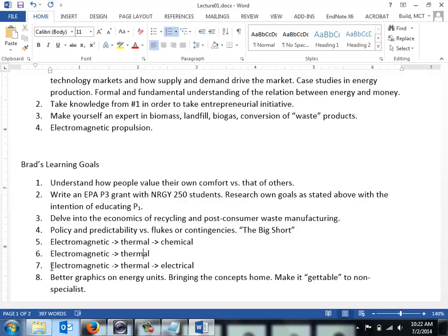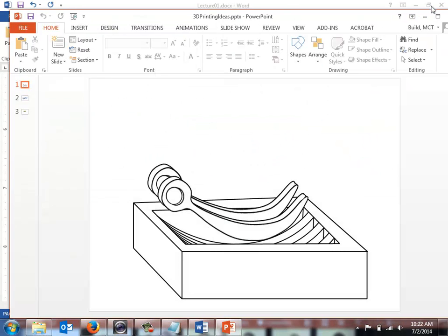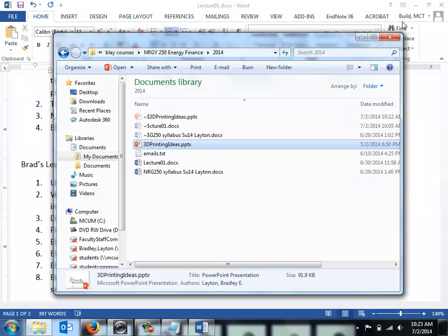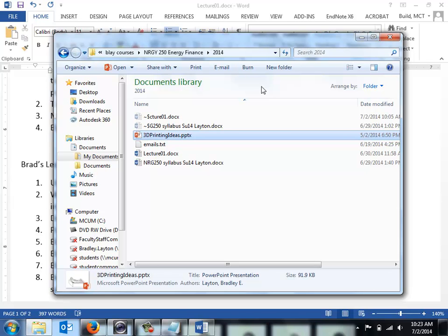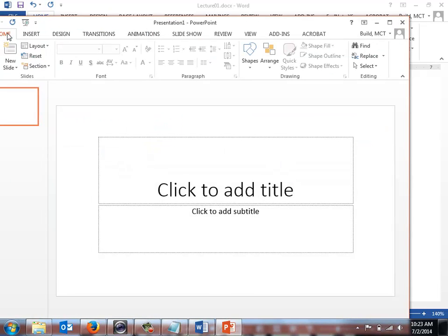Well, it'd be underneath, so you'd have your solar thermal over the top of your PV, and then there'd be your airspace, and the photon would come all the way down in, and capture the heat before it went in, so you get photons. Oh, well, maybe, I think if you did that, you're going to reduce the efficiency. It just depends on how much efficiency you would reduce on the photons going in, because that's what you're looking for, the electrical conversion. And if you heat up your PV cell too much, then you're losing efficiency anyway.